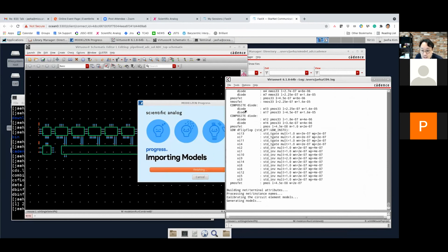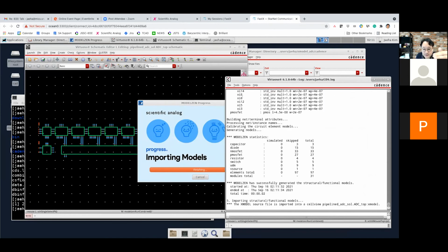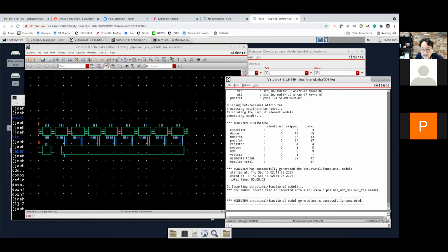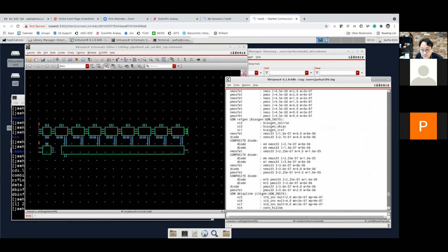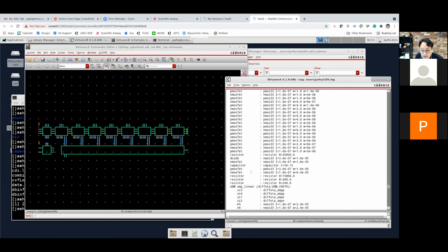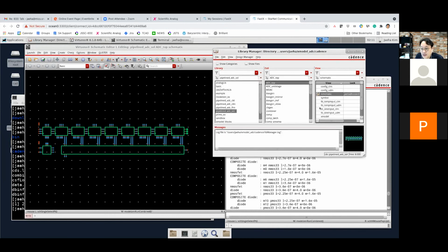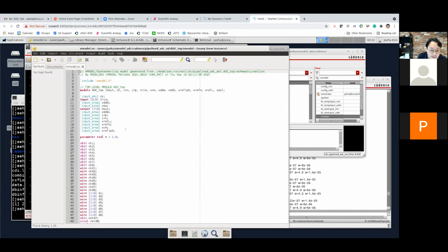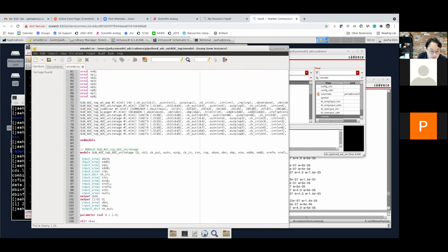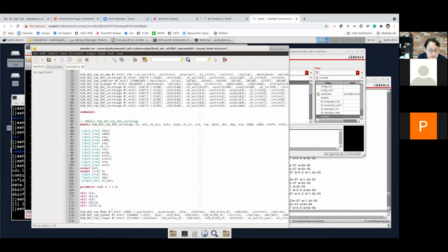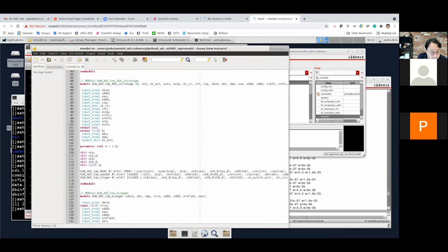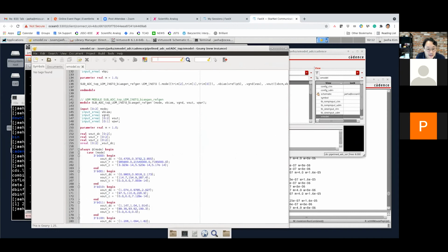Okay, the list of elements went really fast, but it's slightly different than before, because instead of just identifying individual circuit elements, it's also identifying the UDMs that we have mapped, like delay lines, amp linear, and so on. So it's actually characterizing the UDM. Maybe we'll take a look at the model. It's a hierarchical model, so you see multiple modules spanning the whole hierarchy, and probably you'll identify some UDM here.